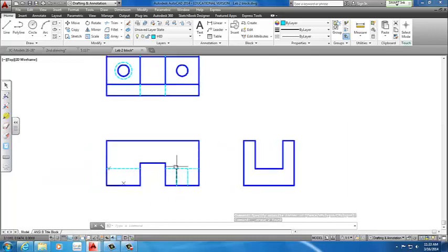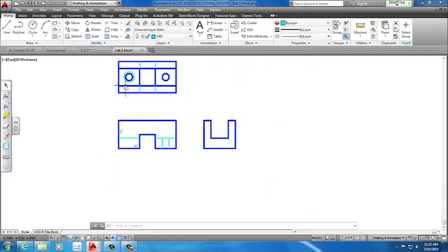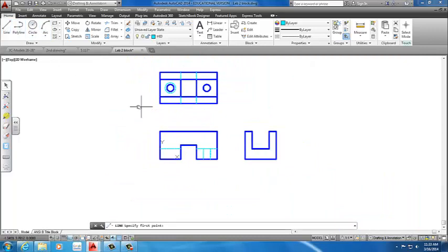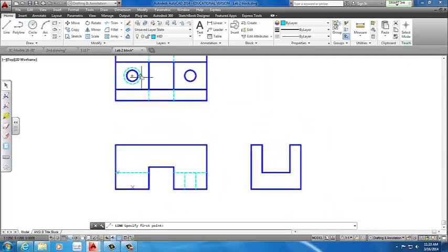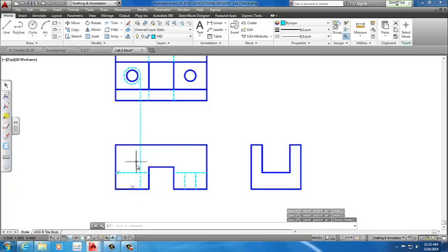We know the thickness of this material, which we showed with a dimension of this circle, 0.52. We do the same thing, except it has two circles. So we're gonna create a circle. It doesn't matter exactly where we place it. So instead of drawing each line separately, I'll show you a little trick. We select this quadrant, go all the way down, and create that line like I showed you. The diameter is 0.52. Or if you want, you can do the radius, which is 0.26. But I just select this line because we need 0.52 to make our diameter.